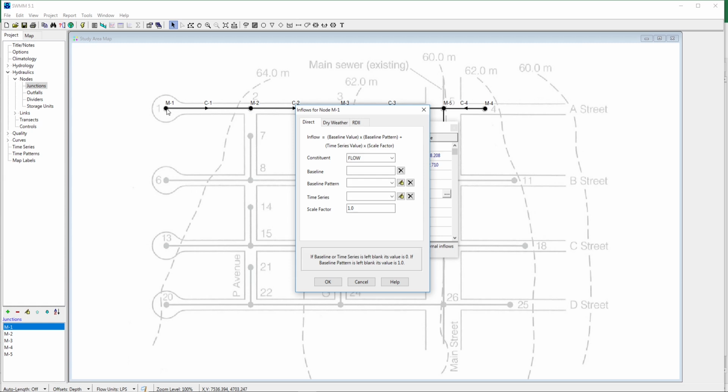So we are going to consider that at manhole number 1 instead of manhole number 2 for this length of the pipe. The first value for I&I that I have, as we saw in our Excel sheet before, was 0.0429, and there is no pattern for that because it is just a constant value, it will stay there forever.